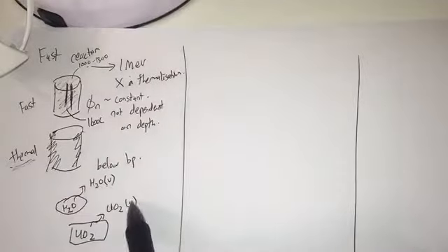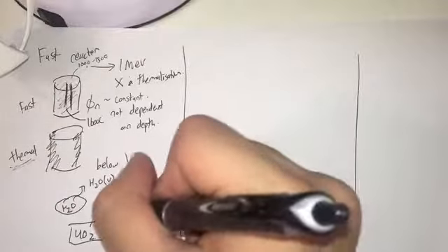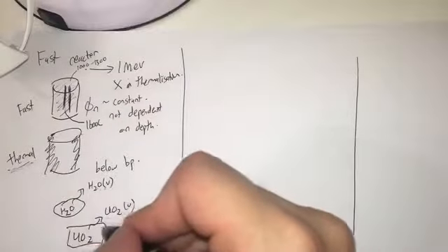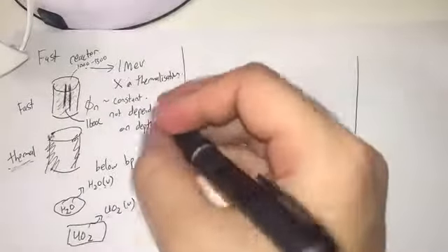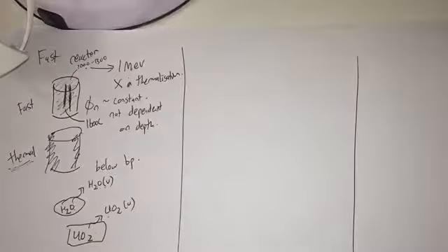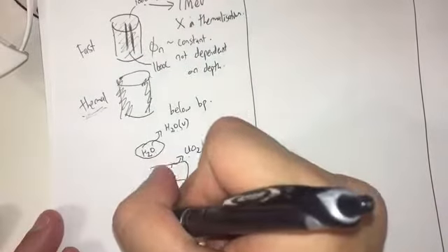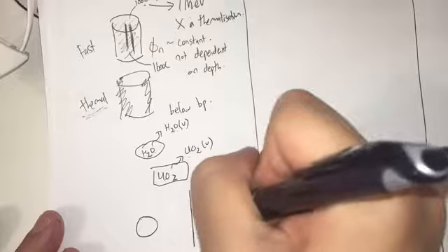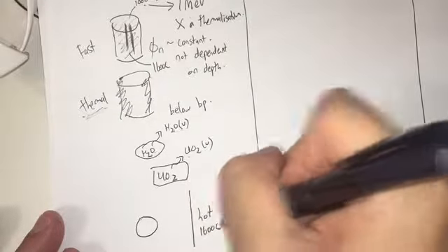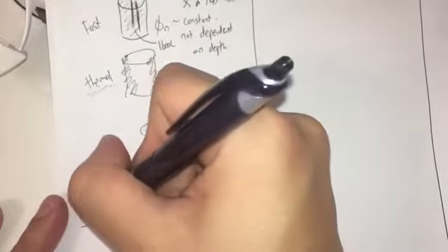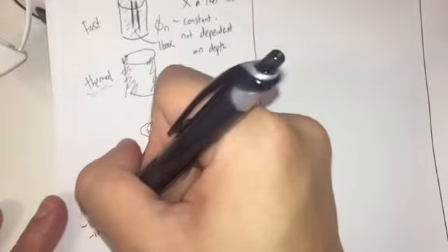Yeah, the solid can do the same thing under high temperature, but below the boiling point, so to speak. But of course, this vapor pressure is much lower than the water. Okay, so what happens? Let's say you have a pore towards the center of the fuel pellet, or towards the central region. So this is the hot side, which is 1600 degrees C, and this is the cold side, which is about 1000 to 1300 degrees C.